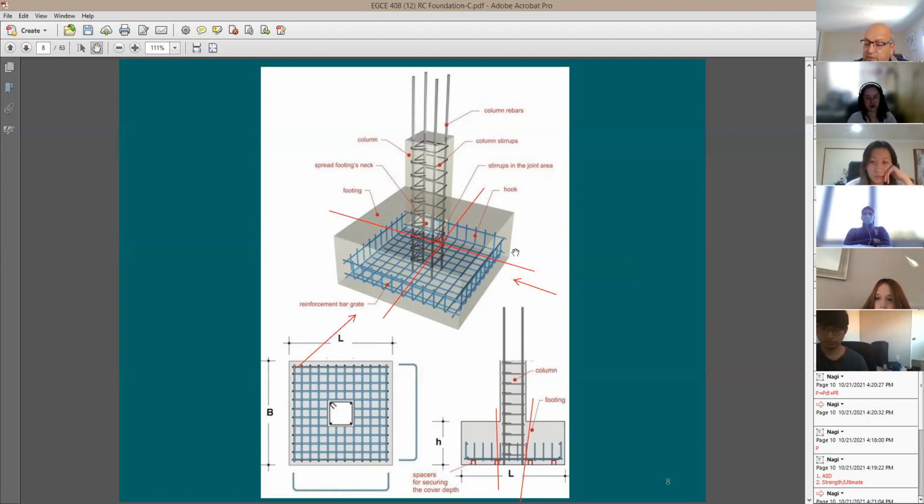And in a case like this, when you also have the same depth, it means reinforcing is going to be the same in both directions. When you have a rectangular footing, you may have different reinforcing at the bottom of the footing. Okay? So I guess this explains that this lifting up of each side of the footing is going to happen as a cantilever case for the footing in both directions.